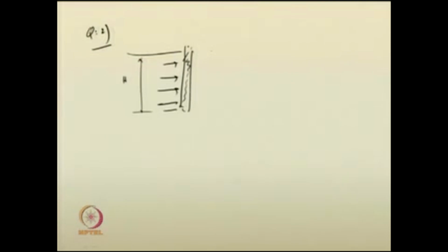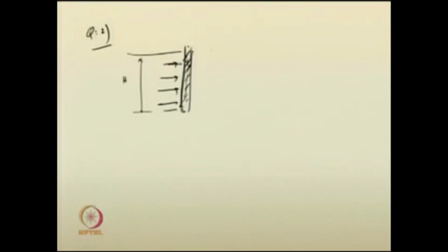The second question we asked is, say in the vertical sluice gate, why you require to design for pressure. Say if a vertical sluice gate is made like this, on the left side water is there. So, water with certain pressure is already there. Now, as a vertical plane has been incorporated, due to the pressure a force acts in the perpendicular direction to this particular plane.